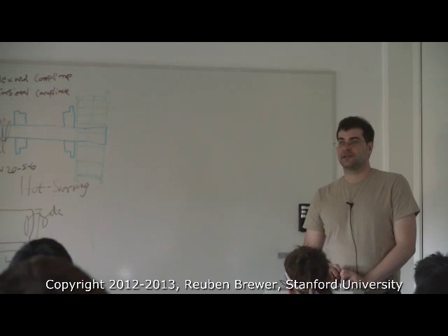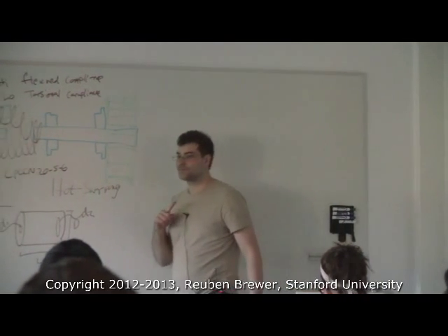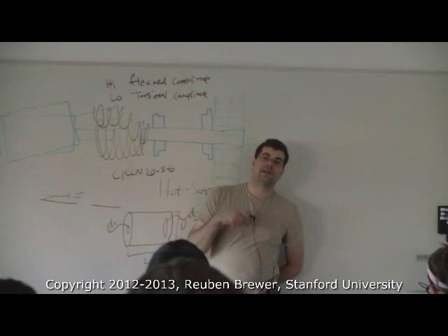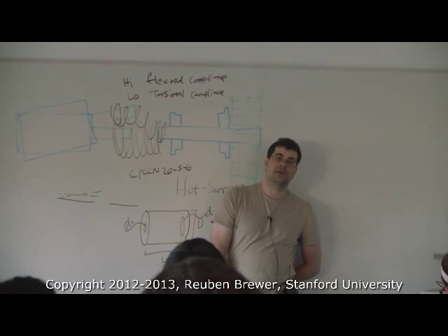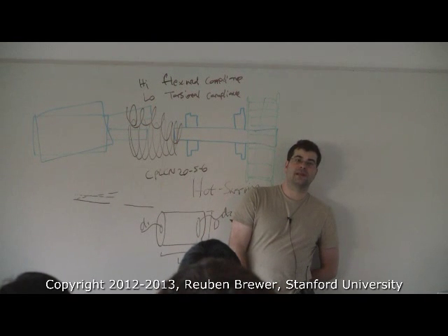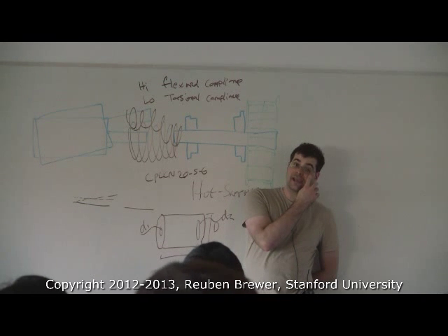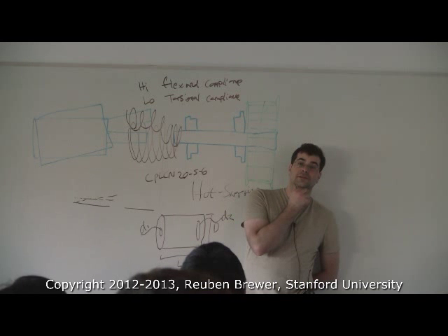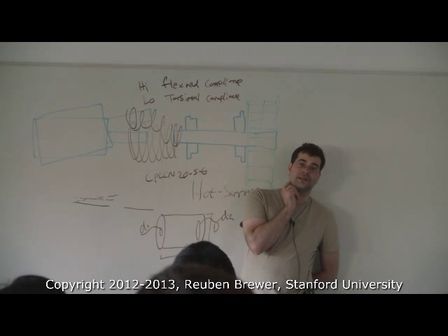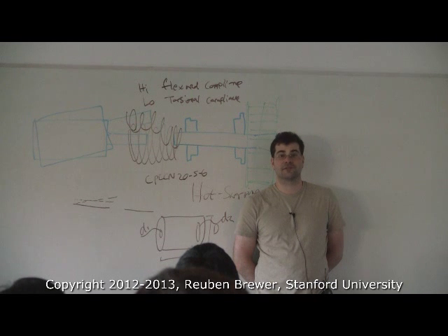I'll give you the hint on the set screw. They vibrate loose constantly. So you tighten it down, then you run the motor for 5 minutes, and it backs out. It's probably going to back out and get lost in your machine. You'll then have to get a new set screw. You will have to service the robot, and if you're me, you'll continually get unlucky, and that set screw will get in between a gear of some type or a slide and will break everything. Set screws suck. Seriously, they're like the devil. I try never to use them unless I absolutely have to, and I've gone to some pretty extreme measures. I've even made my own clamps just so I don't have to use set screws. They are very bad in terms of servicing.